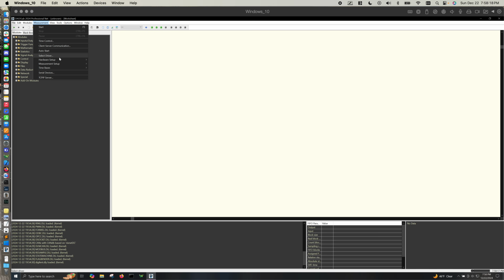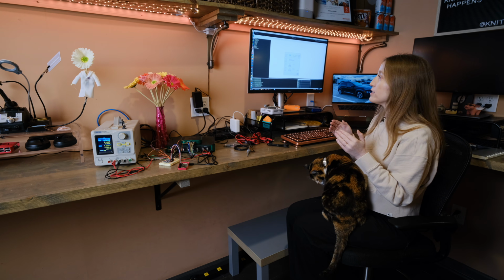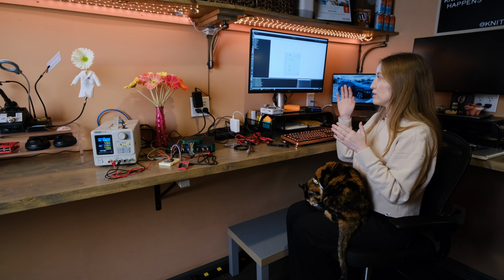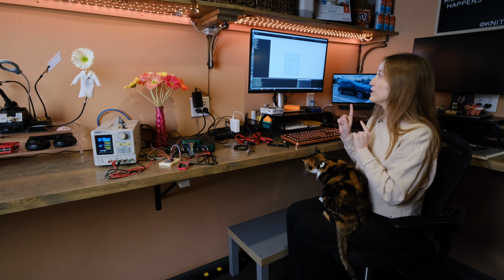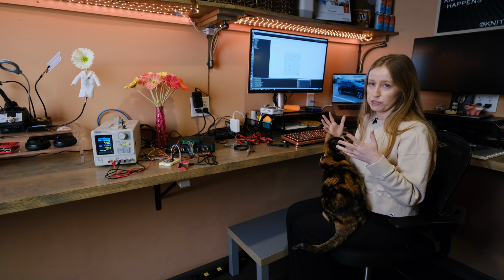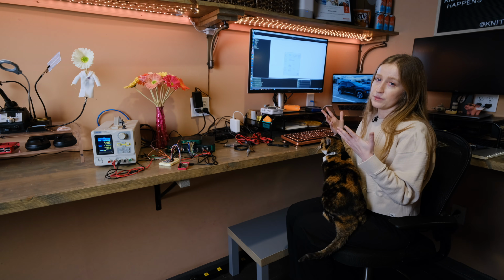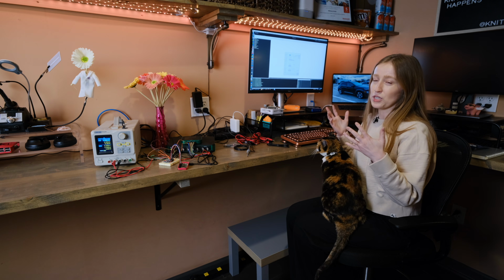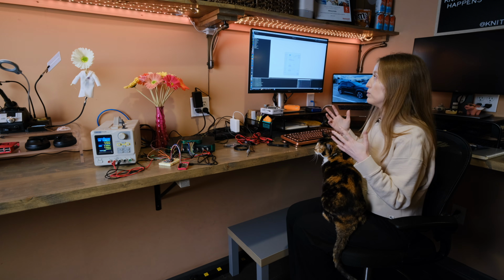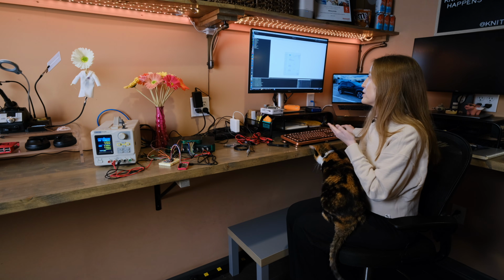That was a little bit new for me to get used to, so coming in under measurement and then driver, this is where you set the overall sampling rate for your whole worksheet. So each block that you put in your worksheet will be running at the sampling rate. Block size is the amount of RAM that your worksheet is going to consume when it's running. If you leave it on specify automatically, you're going to give DASYLab free rein to consume as much memory as it needs, or each individual block. Or you can limit it to a specific number of bytes of memory at a time.